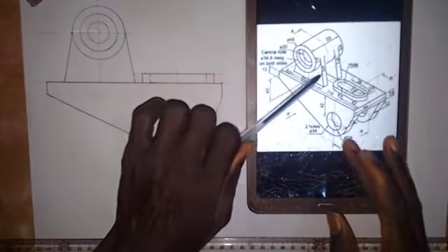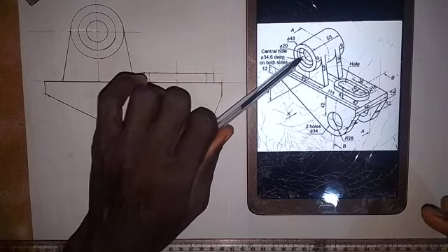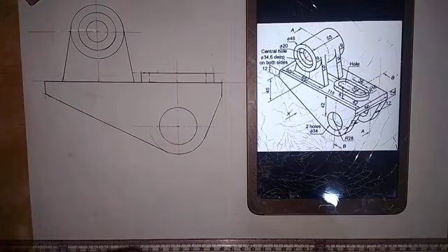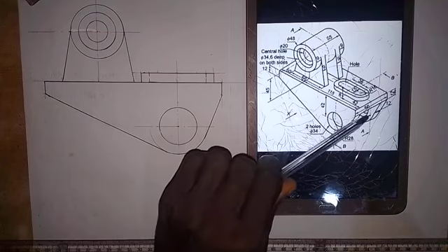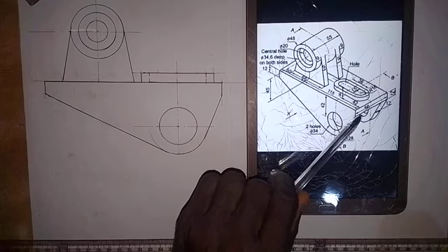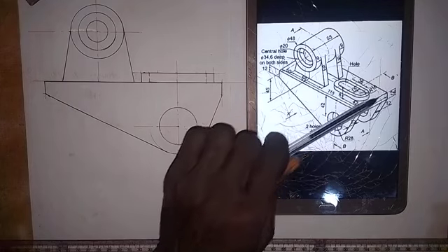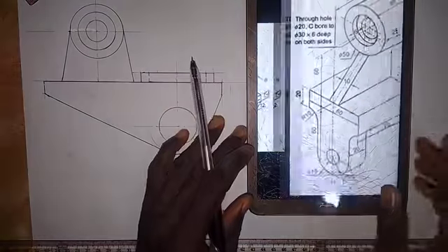So we are going to see this part, and then this cylindrical part, though the circles that we have in it will be hidden from us, so we have to take that into consideration. Also these circles here will be hidden. We also have one within this that will be hidden from us. So there will be a line at this point that will be hidden, and also at this point. The length from here to here is 66 millimeters. So let's work on that.